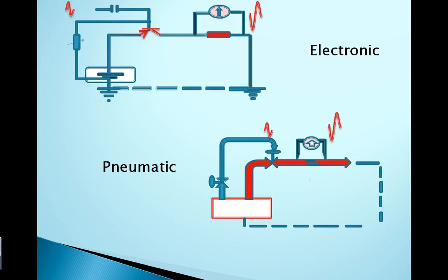The base of the transistor is the equivalent of the diaphragm, and onto that we've put a bias which is coming from a variable resistor that takes the job of the reducing valve. Now, using the base to forward bias the emitter base diode, we can open or shut that particular valve.